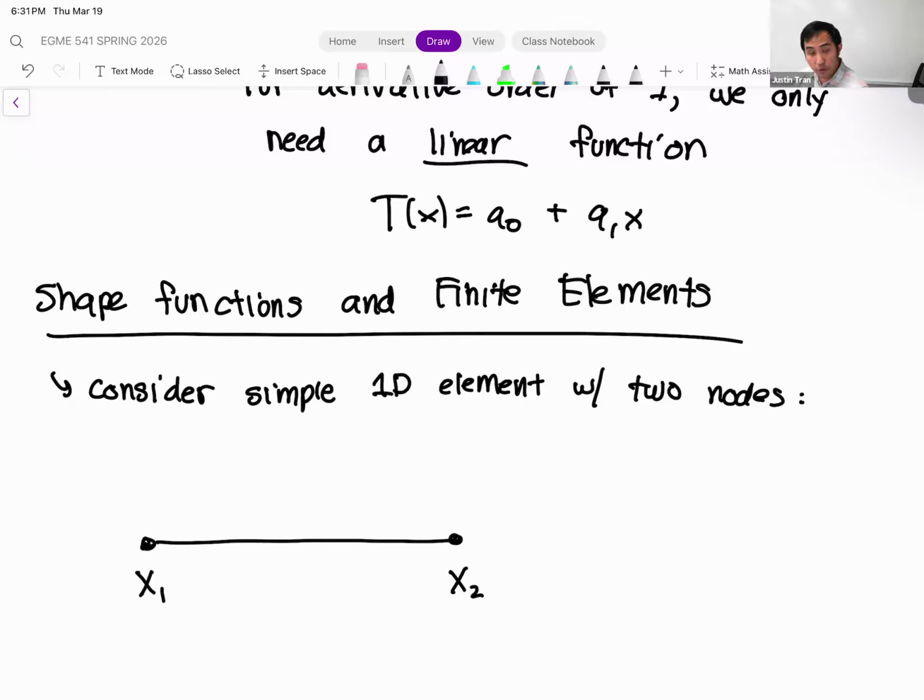The other thing that we're going to assume that we know, and we're going to need to enforce continuity, is let's assume that we also know the nodal solutions. Okay. So left-hand side, I'm going to switch notations a little bit. We're going to have U1 and U2, where these are the nodal solutions. Okay. So remember, the nodal solutions are the solutions to our boundary value problem defined at the nodes. So you can think of the nodal solutions as kind of like our solution, we just sample at those particular locations.